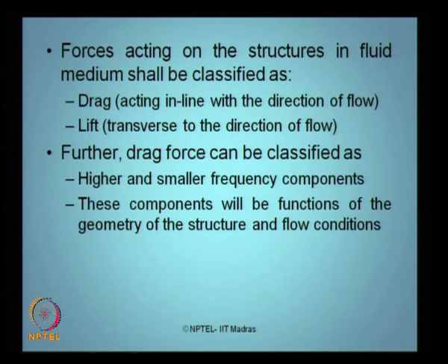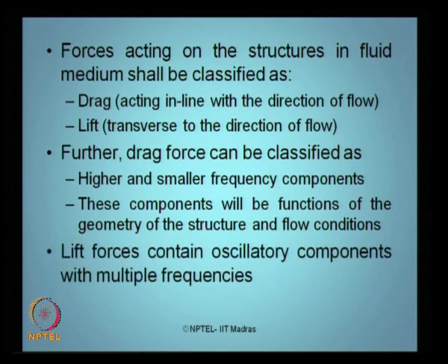These components of course will be a function of geometry, we already saw that, and the flow conditions. So it depends on the geometry of the structural system as well as the flow conditions. Of course, lift forces contain oscillatory components with multiple frequency bands. So very interestingly, when you talk about these two kinds of forces, there are two kinds of response we have seen in dynamic analysis for a given member or structural system.